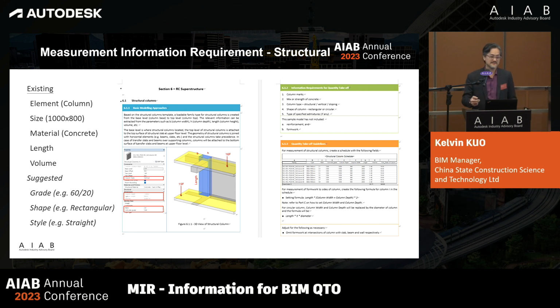Okay, it mentioned that. For example, if it's a load transfer structural element, it should be C60 or something, and for the non-structural one, it should be C30. So actually we have to mention it in the model so that when we extract the quantity directly from the models, we can classify, we can divide it into different strengths. Okay, because in our BQ we need to do classifications according to the SMM. So actually, this is the requirement we need to let the modeling team align with the QS team.